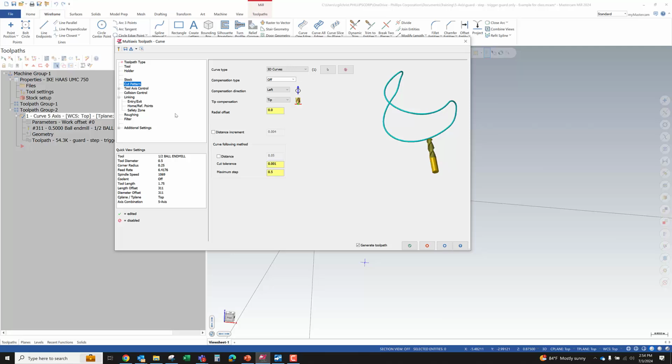How do we move and transition between different cuts that are occurring on the part, whether it's a single chain you're following with curve 5-axis, or whether you're doing curve 5-axis with depth cuts and with multiple stepovers, multi-passes.